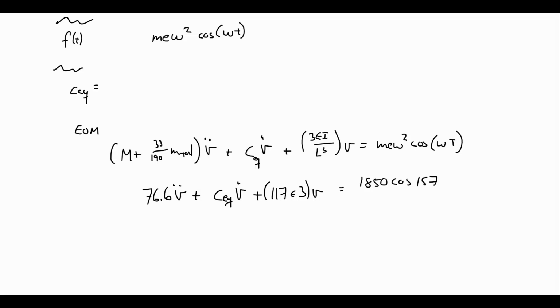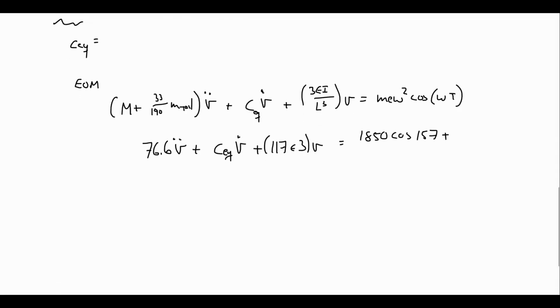So looking at our equation of motion, we can go and see our identify step of what we have going on here. So v is our one dependent variable, so it's 1 degree of freedom. It is going to be linear. It is going to be damped. We know it's underdamped because we are told what the zeta value is going to be, 0.15.